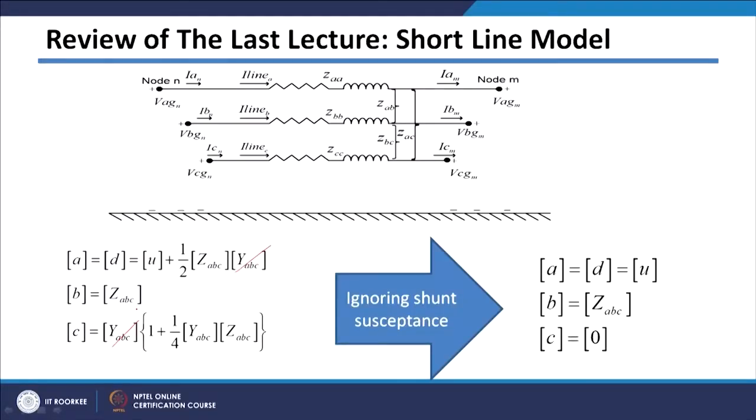Then your short line model will be just like this, where the A and D parameters will be just the unity matrix of size 3 by 3, the B parameter will be the 3 by 3 matrix of series impedances, and the C matrix will be a 3 by 3 matrix of zeros. And as I told you, in most cases we will be using the short line model because the length of a distribution line is short, and in that case the shunt admittance will be negligible.